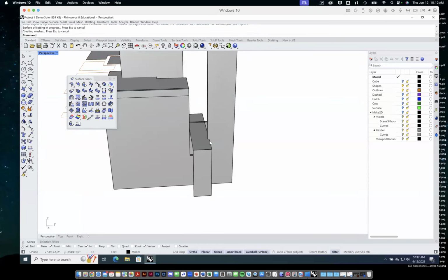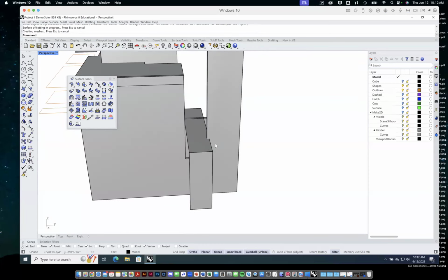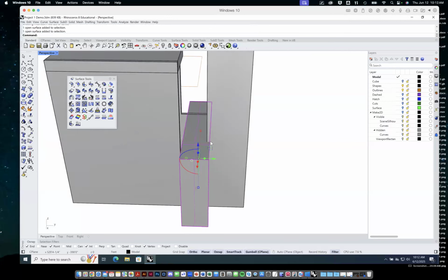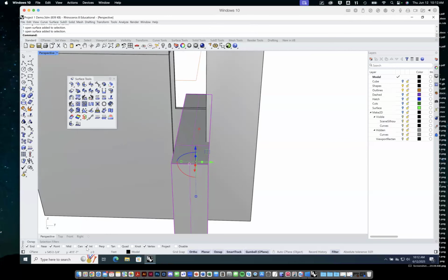Okay, it's really driving me crazy that this is actually intersecting. I'm going to select these two things and move this over. Now in this case, I'm going to use the intersection. I'm going to make sure that the toggle for the object snaps is on. And I'm just going to type in MOVE for the move command. I'm going to find where these two things intersect, hopefully.